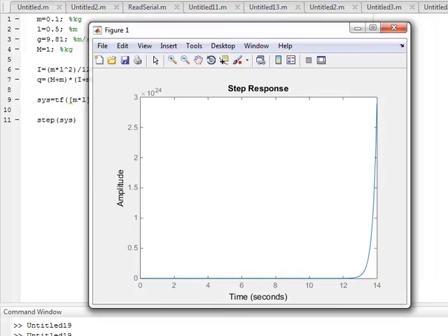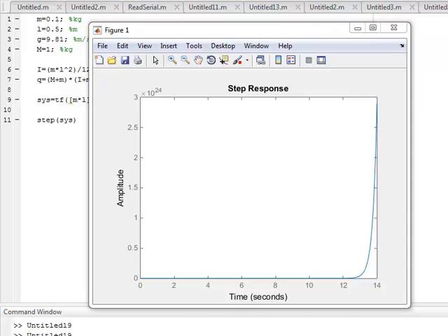Here's the step response of the new system. We can see that the pendulum is still not balanced even though we've added in feedback of the accelerometer. If we think about this just intuitively, we can see why. The sensor will eventually cancel out the drive voltage that we've applied, but not until the rod has already fallen. What we need here is a controller.